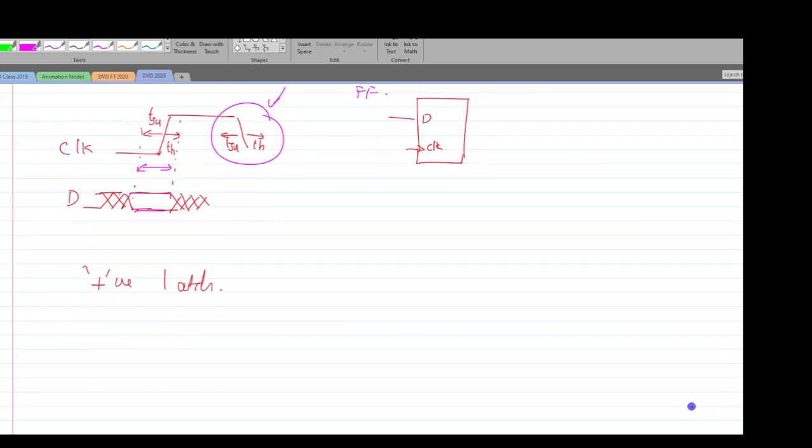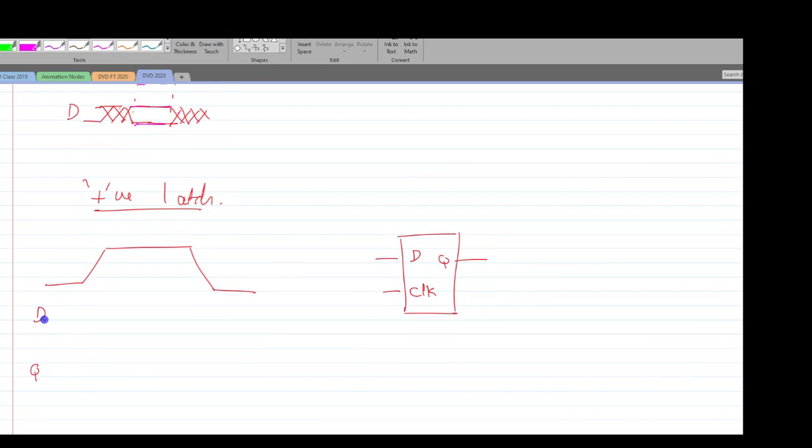Yeah. So now let us focus on what is known as positive latch. As we discussed in our unit second part, we spoke about this latch circuit and also its setup time and hold time, but I'm repeating the same thing just for you to follow in the coming videos. Since the latch is sensitive to the level, throughout the entire period the data is allowed to be read, and throughout this entire zone my output Q is transmitted from the input. Whatever I have across my D is actually reflected at the output.